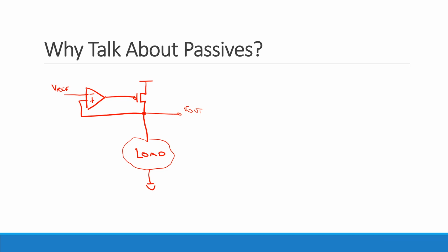So what am I kind of missing? What do you think you are probably going to need in order to actually build this and get it to work? A cap. Okay, where do you want to put the cap? So you want to put a cap on this so-called V out, and presumably you want to put that to ground, right? Okay, why do you want that cap? So that's usually called a decoupling capacitor, right? You want to make sure that the output stays relatively constant. Right? So let's call that CD cap. Okay, I agree with you. You probably want that cap.